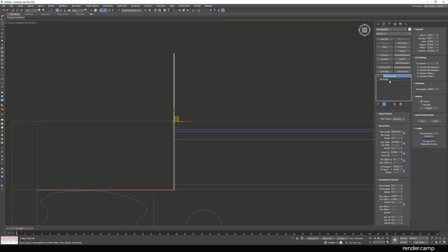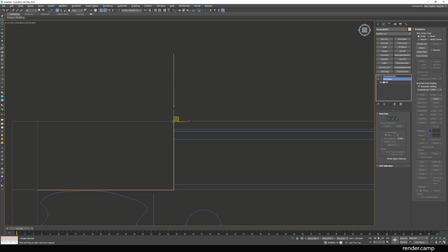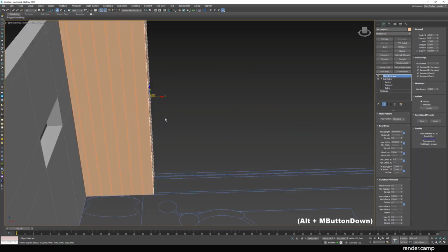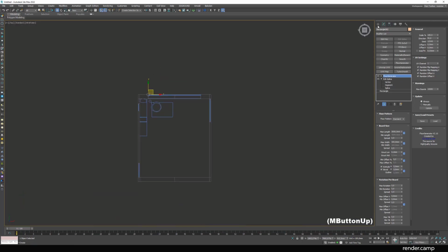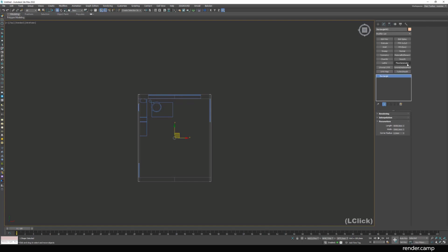Go down to Rectangle, add Edit Spline. You can find it in the Modify list. Open it, pick Vertex, select in the viewport and move with the snap. Exit Vertex and back to the Floor Generator. We have created panels for two walls. Now we'll do floor. Switch to the top view, Create tab, select Rectangle. Create it with a snap. Go to Modify, add Floor Generator.